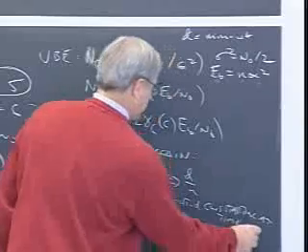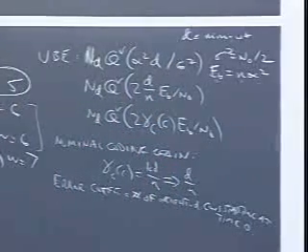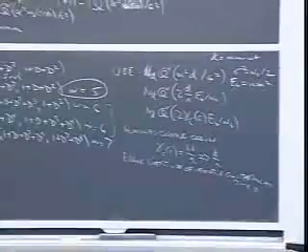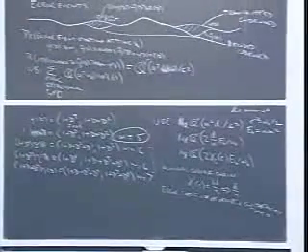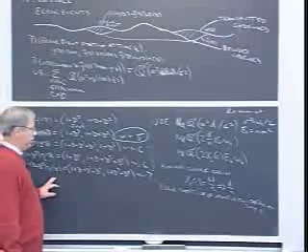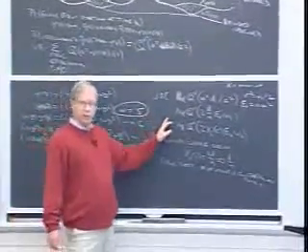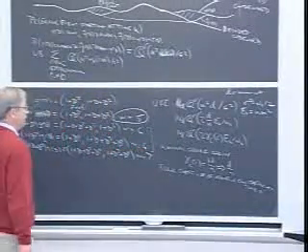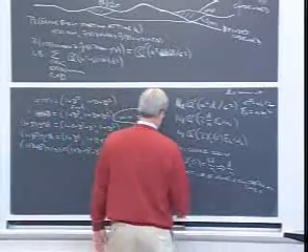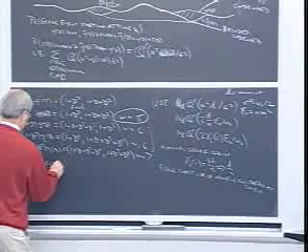Of course, an error event could start at any time. If there are nd starting at time 0, how many start at time 1? It's time invariant code. All right, so it's going to be the same numbers could possibly start at time 1. So what I'm computing here is the probability of an error event starting at a particular time. For this particular code, I have, what do I have? I have one event of weight 5.